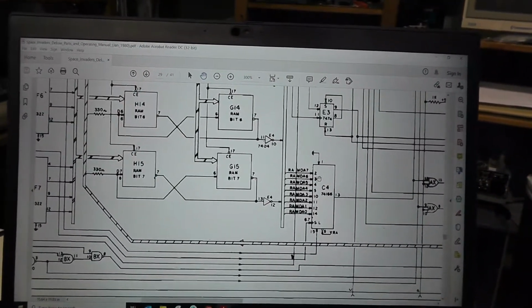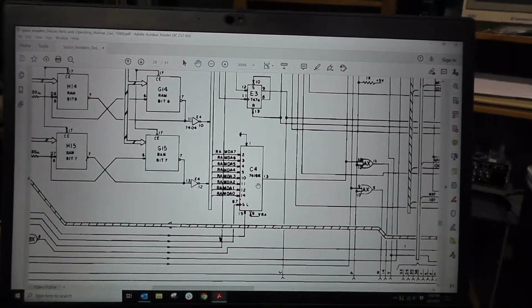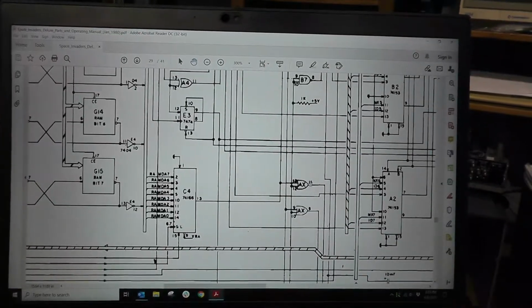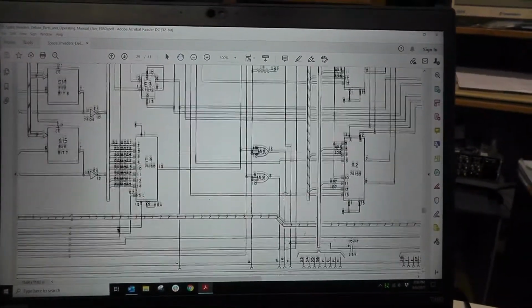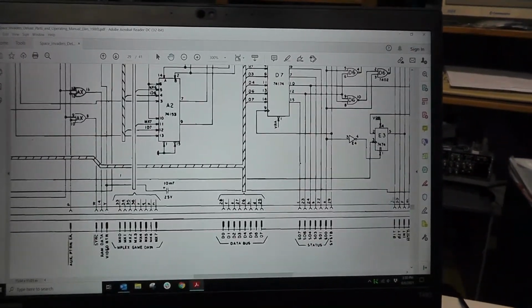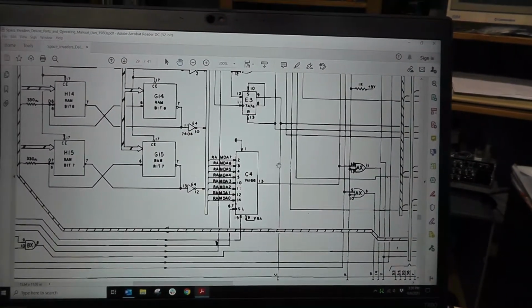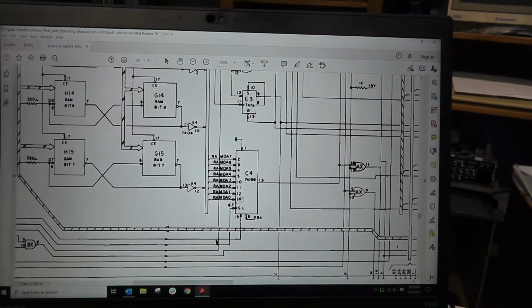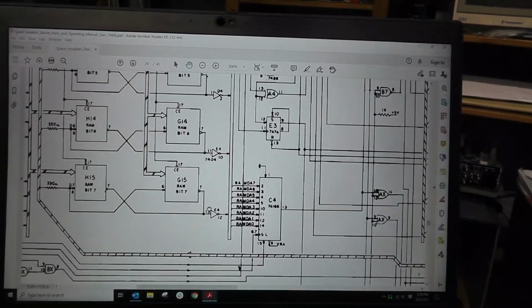And then the video data comes to the 74166 that we had previously replaced, goes through this resistor, comes down here, and is ultimately your video out, right? So the RAM data goes straight into the 74166, gets combined, and there's your video going out to the screen.